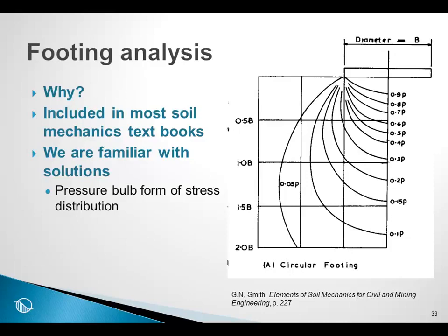It is rather a curious example because we never build footings on the ground surface. However, this type of example exists in all textbooks, and as a result, everybody is very familiar with the Boussinesq pressure bulb beneath a footing, and consequently we have an appreciation before the analysis of what the stress distribution should look like after we apply our footing pressure.